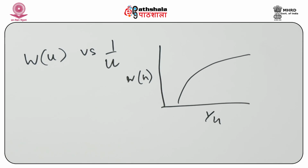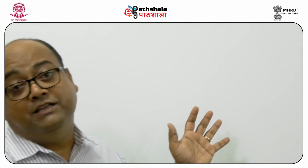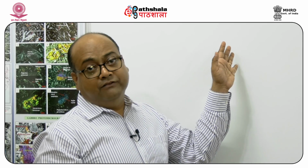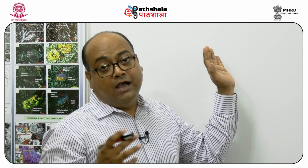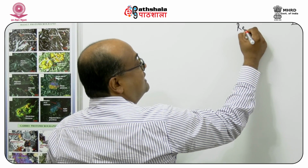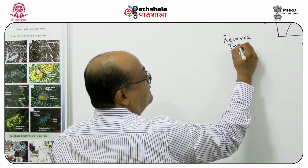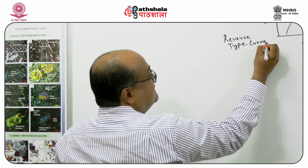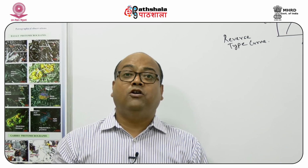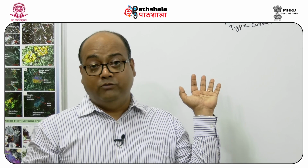The shape of the curve is almost like the depression of a water table, and it is a standard curve found in any book of hydrogeology. This is known as the reverse type curve, and it is used for the graphical solution of the Theis formula.